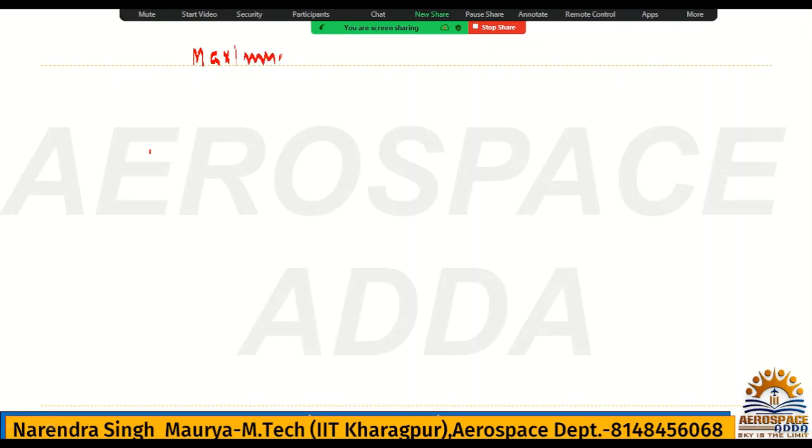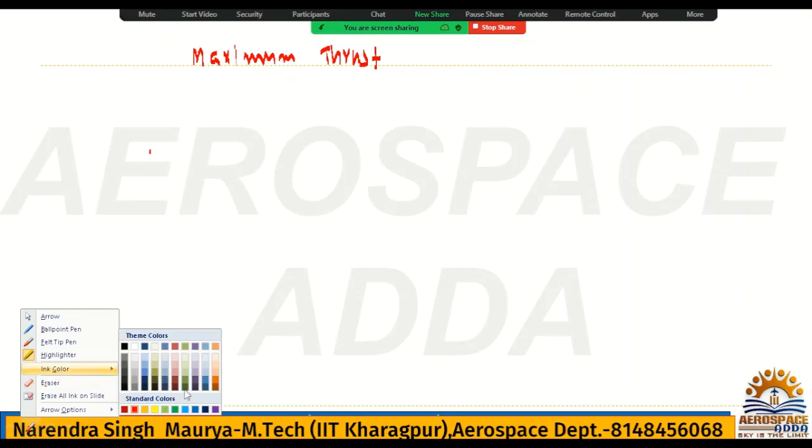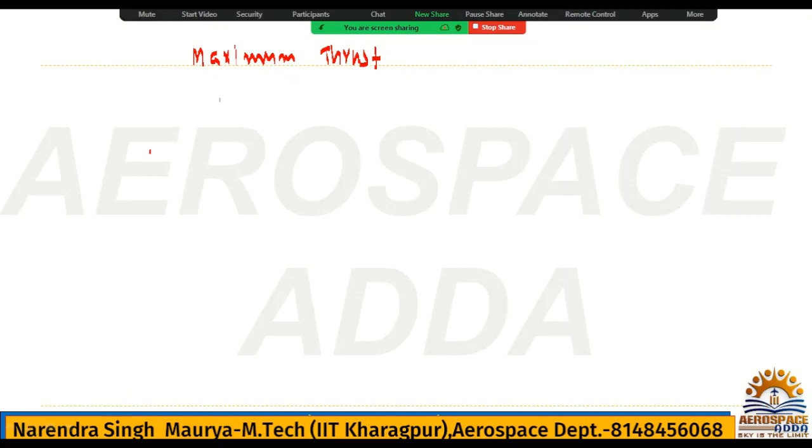Condition for maximum thrust. If you check the standard formula of the thrust for rocket, it is nothing but T is equal to m dot p into VE plus PE minus PA into AE.